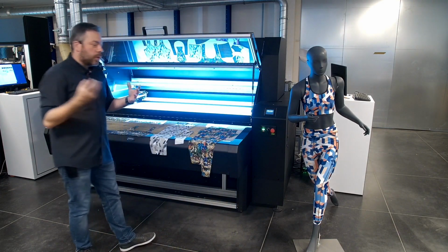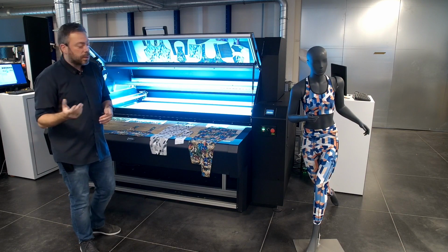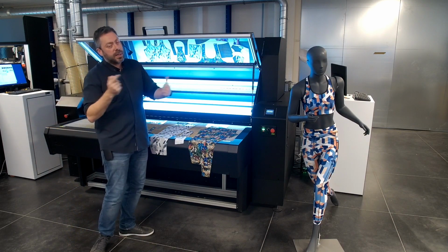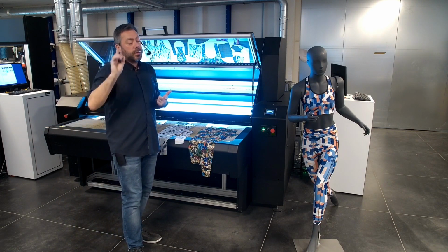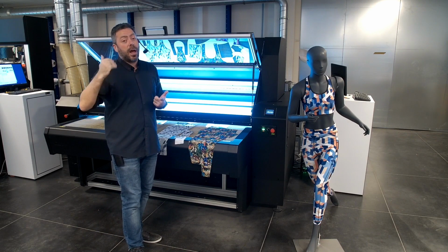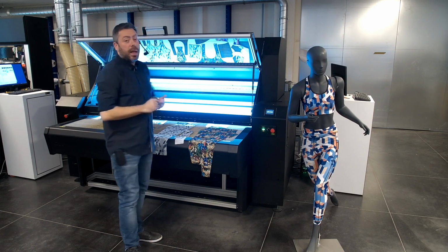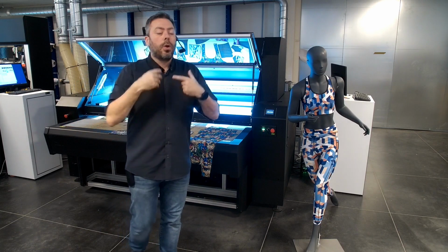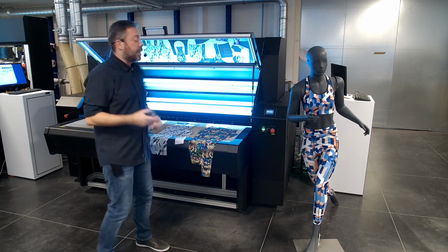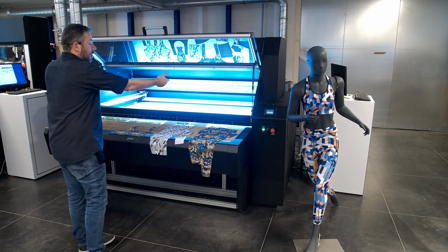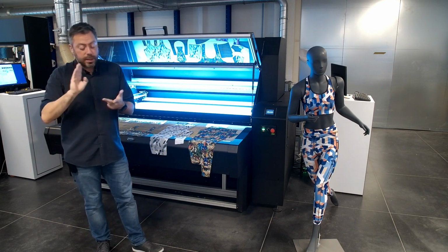So generally those are two major points for cutting with the laser, especially cutting with a vision. It generates the files automatically, or it generates the cut paths automatically. We generate automatically a waste cut. That waste cut, before I forget, can be defined how many times it's going to do. So it's either going to be for every scan, every 2 scans, every 3 scans, every 4 scans. So you have some influence on that. You can even switch it off if you want, but then you need to realize that it could basically be heavy and it could slightly influence what is being cut there. So waste cut, no files needed.